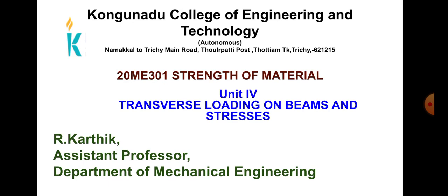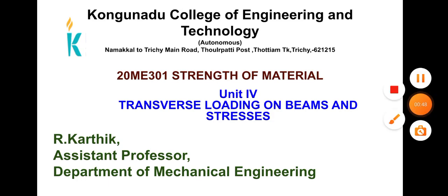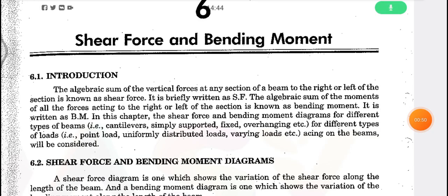What type of stresses will be created there, what is the maximum bending moment, and where the maximum bending moment will occur inside the length of the beam. We also have to find out the maximum load. That should be derived from the shear force and bending moment.